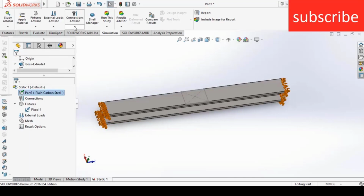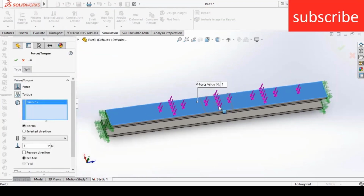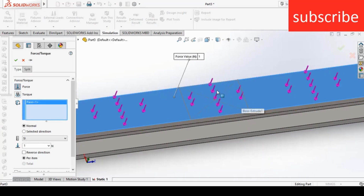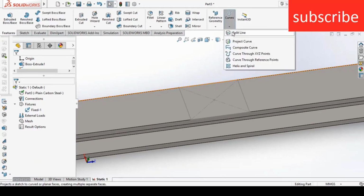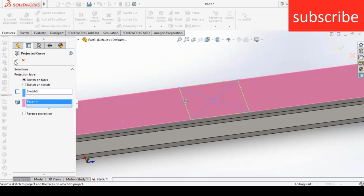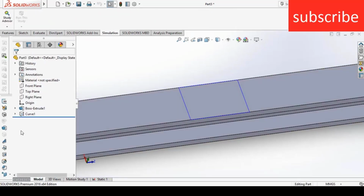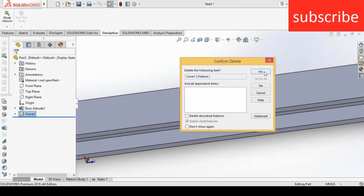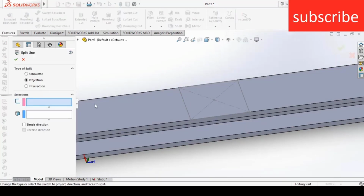Now here comes the important thing, click on force. When I try to click on force, as you can see I am selecting the whole beam, but I just want to select this particular sketch. So how can I do that? To do that, what I need to do is projection. Go to features, select curves, click on project curve, select this sketch. After that in here select the face, click OK. Now you can see, oh sorry, I guess I am doing something wrong. Right click on it, delete. Yes, I need to select split line, sorry for my mistake.